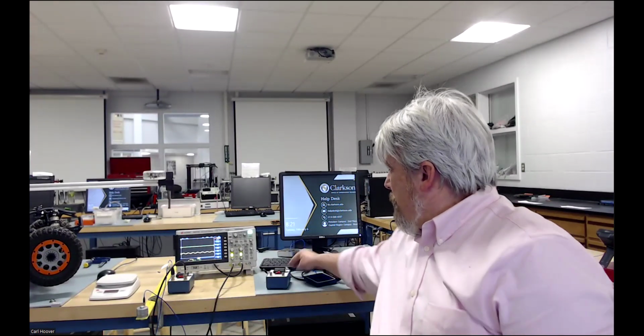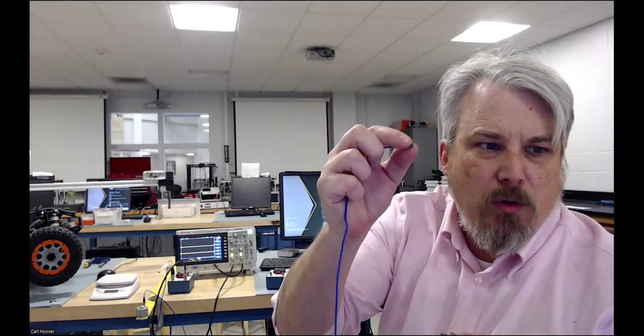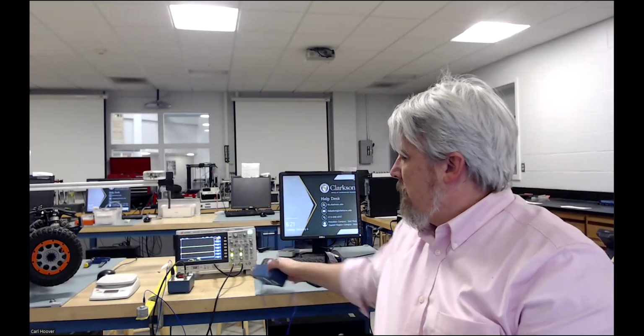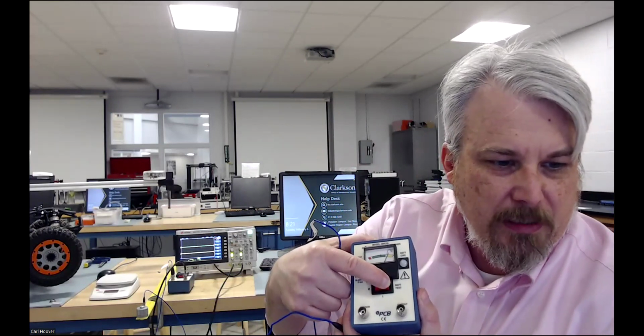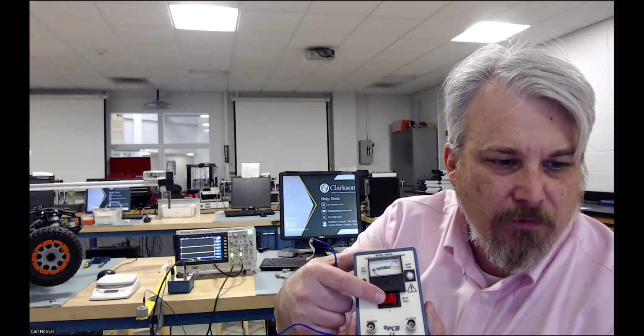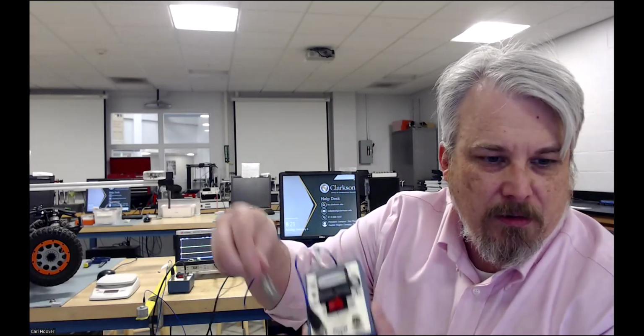Okay, so the accelerometer gets connected through a small coax cable like this to a normal BNC connection to this little guy, which is a battery-powered charge amplifier. So you can check to see if the battery's working by just testing here. When it's in the middle position, it's in normal operation. Over here, it's off. Make sure that you turn it off when you're done with the test so we don't drain the batteries. This BNC gets connected here.